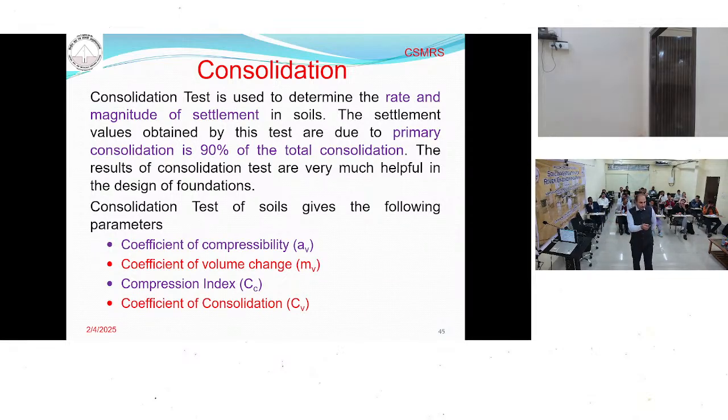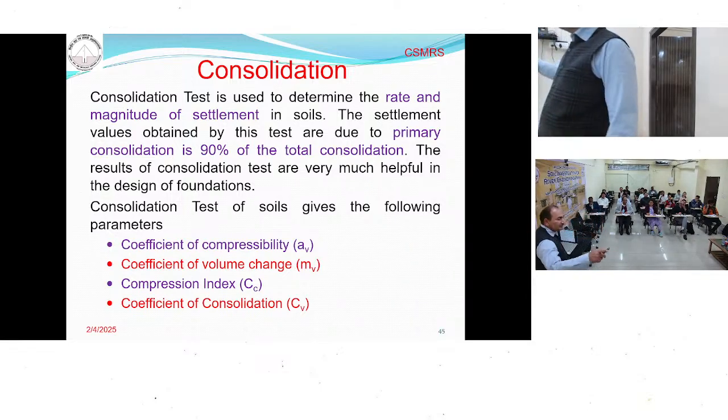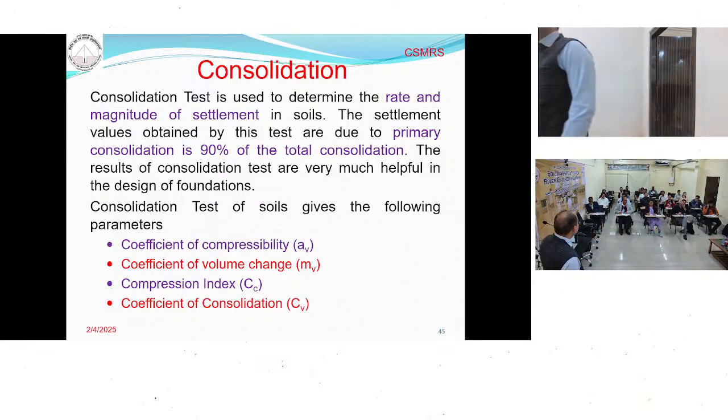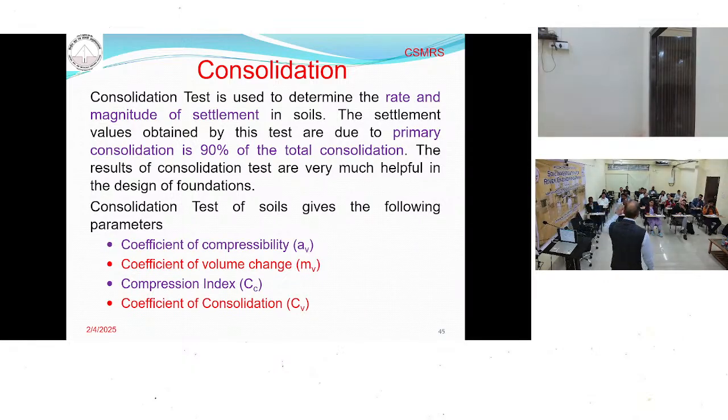The most important is the coefficient of consolidation. We are interested in that, and in the coefficient of volume change. How much volume is going to change? It will tell how much your structure is going to settle.